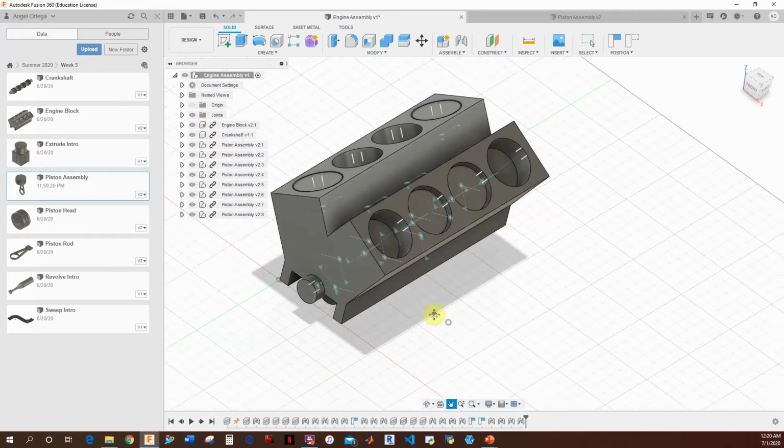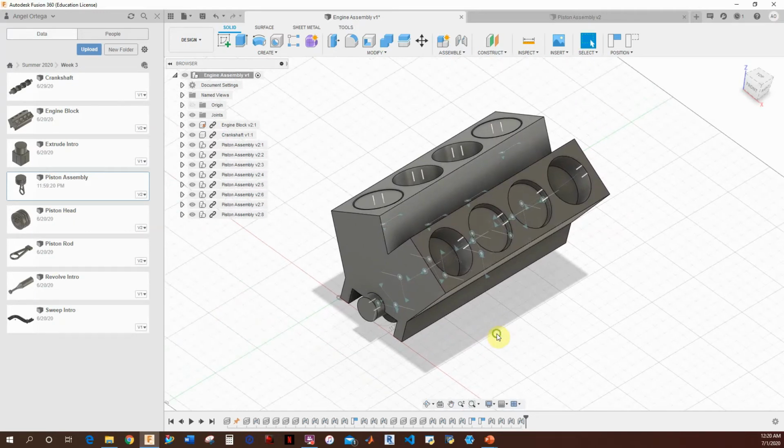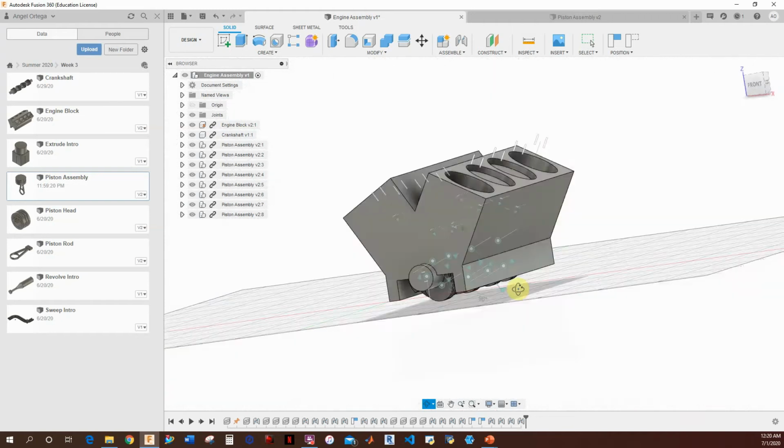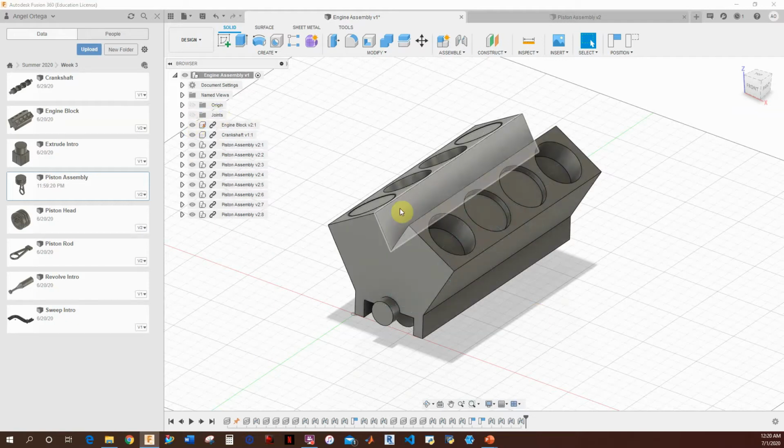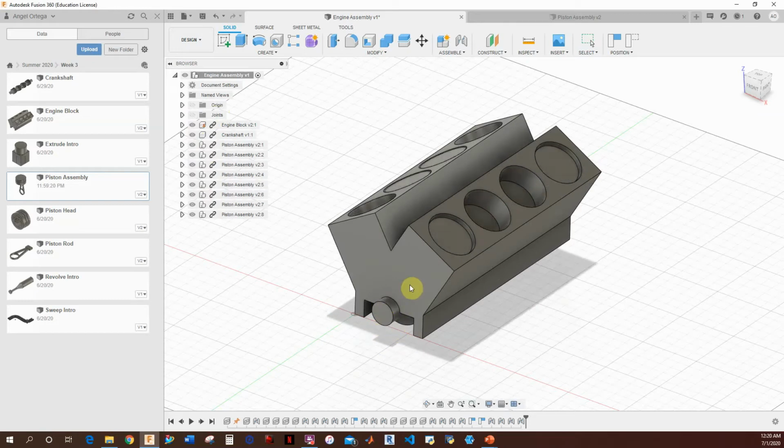Okay, now finally, the only thing left to do here is I'm just going to turn off all of the joints that I can see here, just because they look very messy. Okay, so what I'll do is I'll look for joints, turn them off, and even though the joints are still there, they're no longer visible. Okay, and all I need to do is save this file.